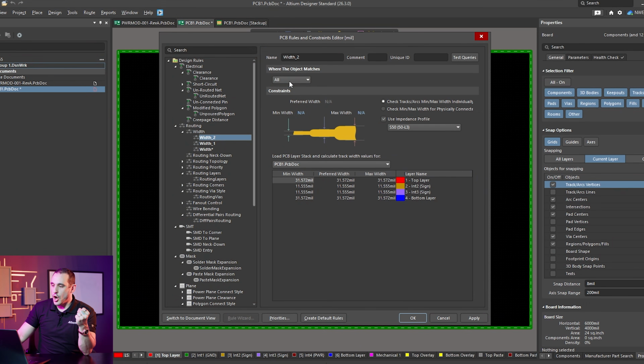And I think you can do it a couple of different ways. One way is to create two different RF nets with our different widths and then connect them together with a net tie. So here in this scope, we would then want to apply this to the different nets that we set up in the schematic. And to do that, we would just use the net scope option. We would then select net number 1 in this dropdown. And then for the other impedance profile, we would still use the net scope, but then we would select the other net in this dropdown. And that allows us to use the two impedance profiles that we calculated in the stackup manager.